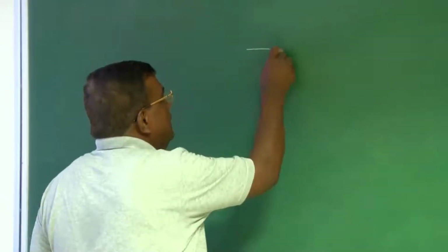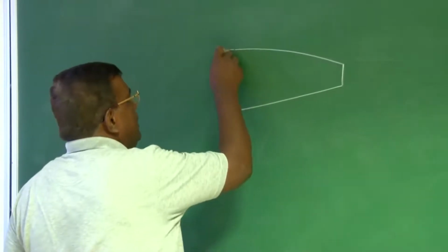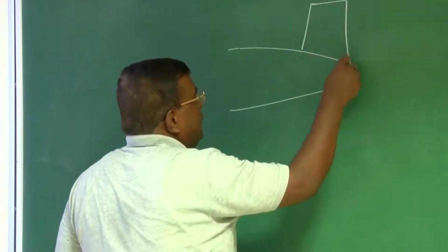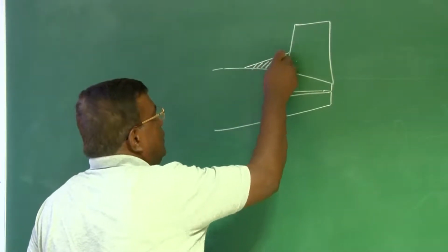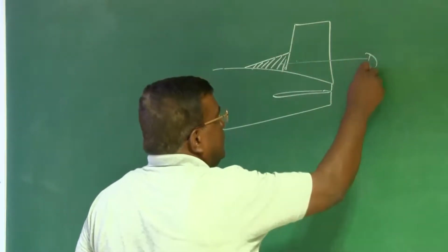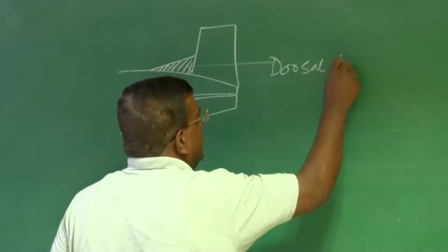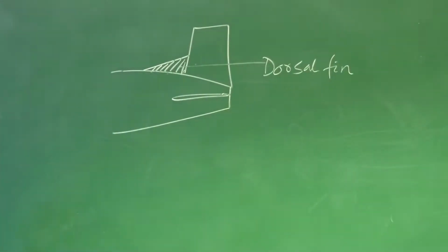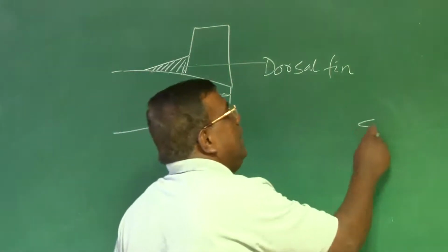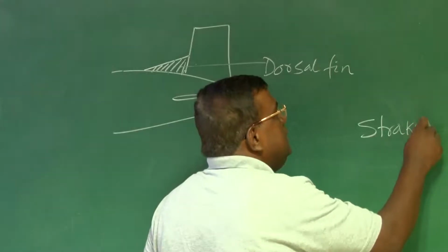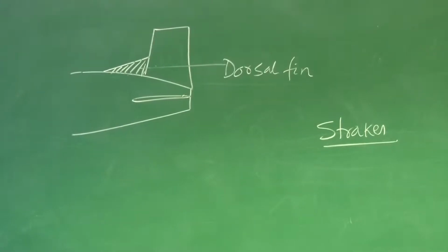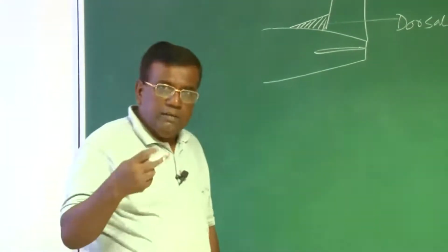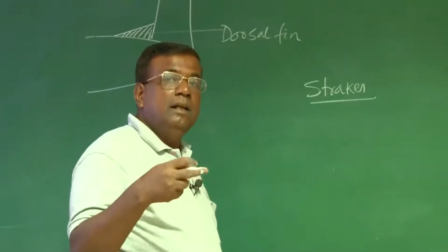Also, you might have seen the empennage, the part where the vertical fin, etc., are housed. There is something like this. We call it the dorsal fin. These are basically strakes, if you want to understand from the aerodynamics language. What are aerodynamic strakes? What is their role? Their role is to generate vortex, so that there is enhancement in the lifting capability.